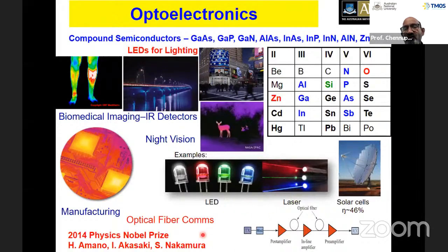So today I'm able to talk to you by using optical fiber communications. The signals from my computer have been converted into an optical signal using lasers. Then you have an optical modulator, which is nothing but an optical switch, and you send the information on and off through an optical fiber. Then you convert this optical signal into an electrical signal again using photodetectors.